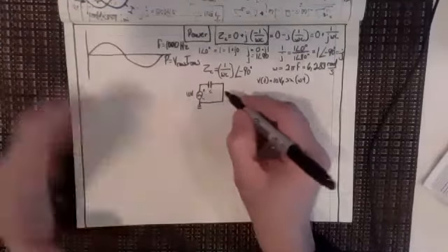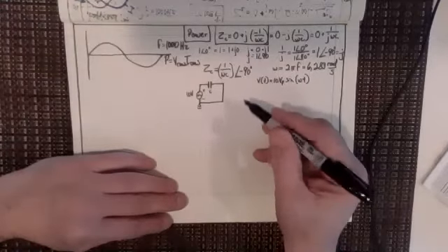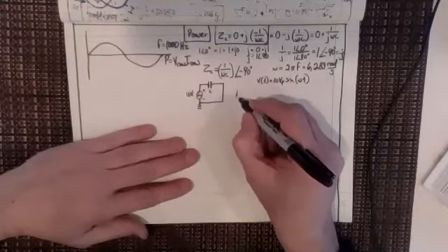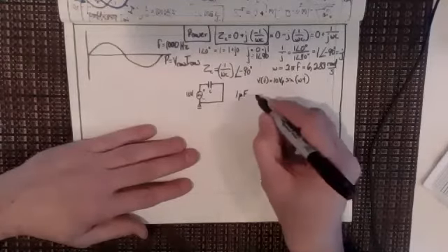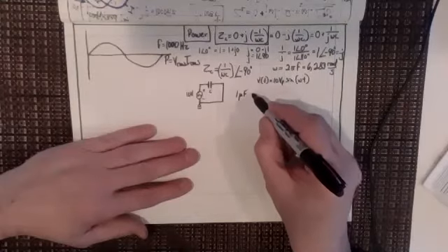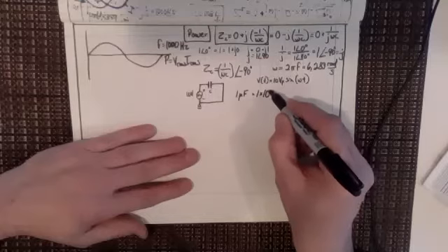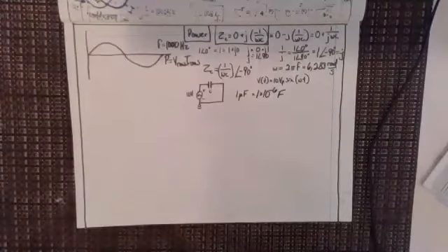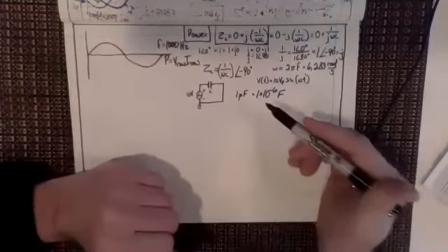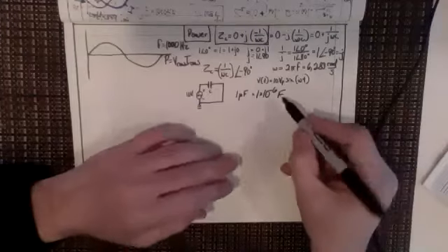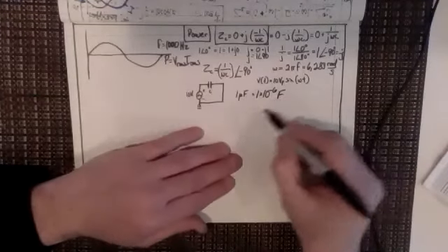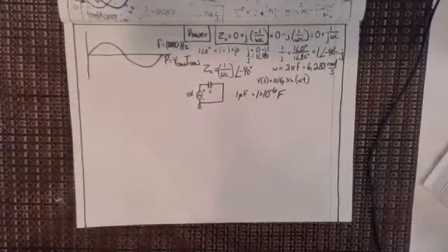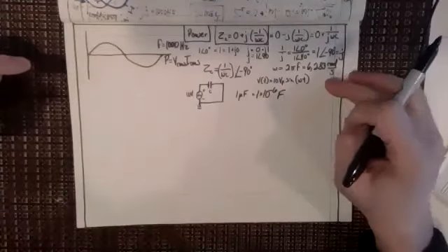Now, we've got some type of capacitance too. Let's actually pick some type of capacitor. Let's say a 1 microfarad capacitor, right? Now 1 microfarad would be 1 times 10 to the minus 6 farads. And we've got to keep it in farads because we have to multiply consistent primary unit combinations that we give nicknames to, like a farad, so that we know that when we talk about farads, we're talking about kilograms, meters, seconds, amps, those primary units all put together correctly.